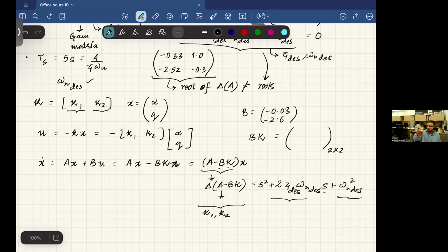and then that sensor sends the data to a computer. The computer is connected to a servo, and the servo has an amplifier before that. So the K1 and K2 that you calculate tell me what kind of amplifier, capacitor, resistor, and inductor I should use to get that value of amplification. K is basically the value of amplification. You connect the servo, and now the computer controls the aircraft on its own. The pilot doesn't have to do anything, and the pilot thinks, oh, this aircraft has level 1 flying capabilities, when originally, without the automatic control system, it did not have level 1 flying qualities.